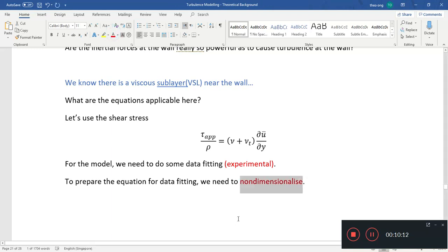So remember, for example, we have this pipe friction coefficient. We wanted to experimentally determine the friction coefficient of the pipe as a function of the flow properties. What we see in general is a chart that describes how the pipe friction changes as a result of the Reynolds number.